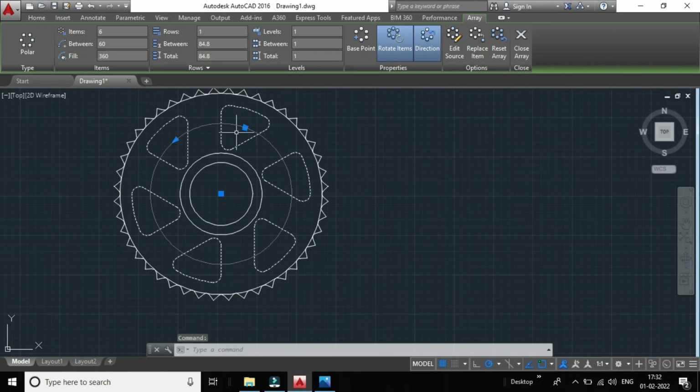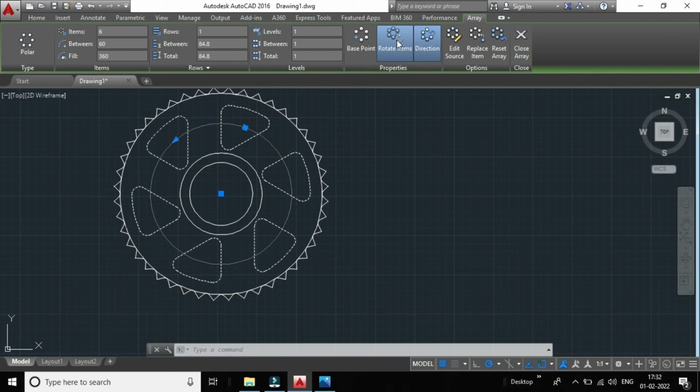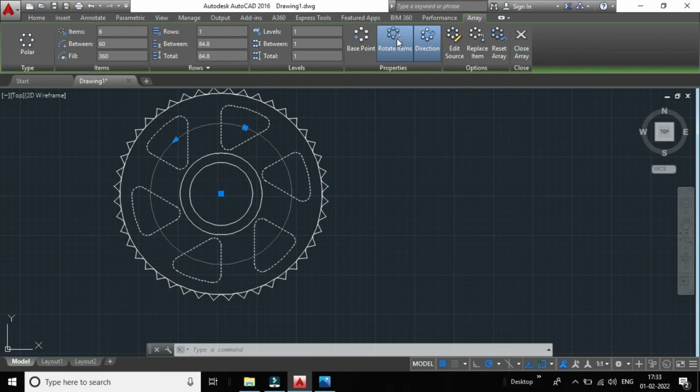Click on this circle option, and let us give the diameter as 10. Click on the center option here. Next click on this array option, and let us select these objects and click on the center option. We have to specify the center point of the array. Click on this. Here the holes have been given. Let me select the circles and click on the delete option.